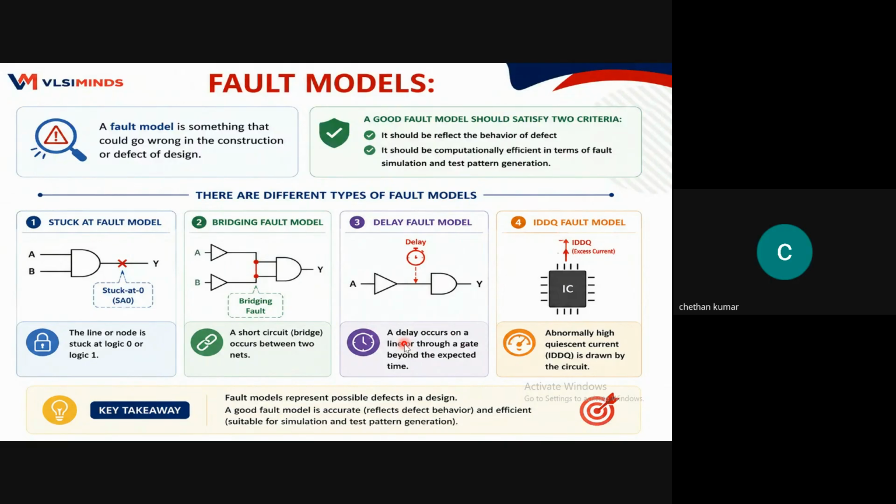Usually how it goes is, as a DFT engineer, we deliver the scan inserted netlist to the PD team. They will do the placement, routing, all those things, and then they will give the PNR netlist to us. In the meantime, they will also deliver it to the STA team. The STA team will be responsible for closing all the timing issues, and they will give us the SDC and SDF files. Based on those SDF files, we have to simulate it. That is called timing simulation.